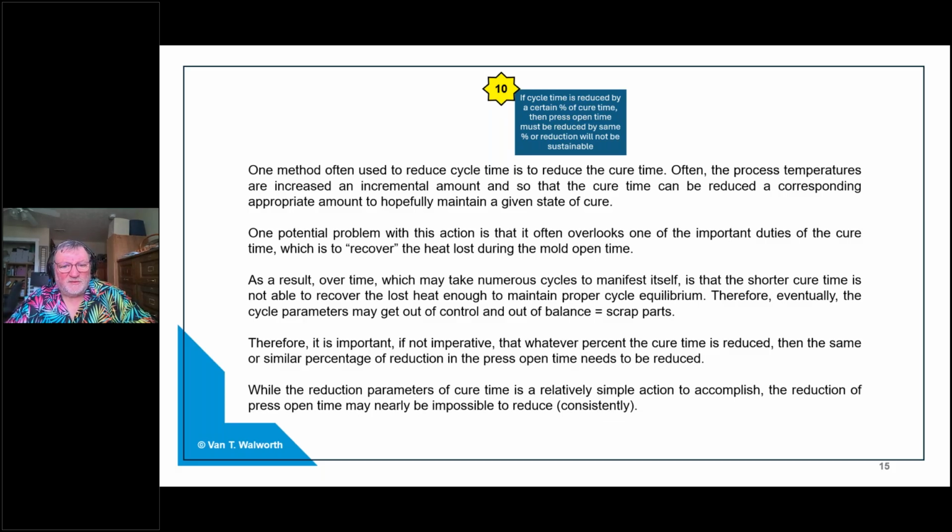And there are a lot of experiments about that available that have been going on for a long time. So theoretically, I can shorten cycle time by elevating my curing temperature if the rubber will allow it. And we do that. People will try to shorten the cycle time by taking it out of the cure time. And that works fairly well. People do it all the time. Process engineers are well known for coming up to a press, raising the temperature a few degrees, shortening the cure time, which then shortens the actual cycle of the press from gate to gate.